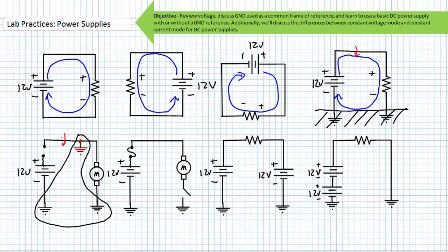Consider the exact same scenario for a low side switching arrangement. In the event of an errant connection to ground, on this side of the switch, there now exists a path for current, despite the fact that the switch is open. Because again, despite there being 3 separate symbols, it really means that those are all pooled to one point of common connection.